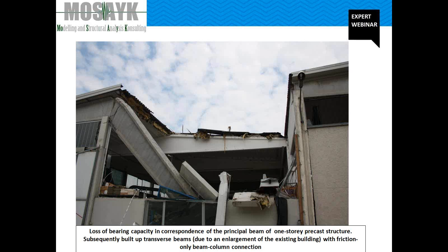An intrinsic, let's say, lack of shear and ductility capacity has been observed in simply supported beam to joist and beam to column connections, primarily constituted by vertical steel dowels or relying on shear friction with or without pads, like, let's say, neoprene pads.